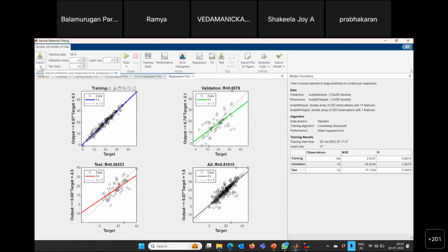Accordingly, I can check in what direction I have to move, either in the positive direction or the negative direction. So I'll consider two inputs. One is the error, and the other is the rate of change of error. For my given control input, whether the error is increasing or decreasing, accordingly I have to modify my input, which means I have to take my control action accordingly, right? This is the way we implemented it.